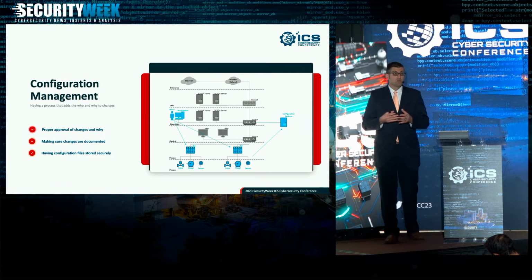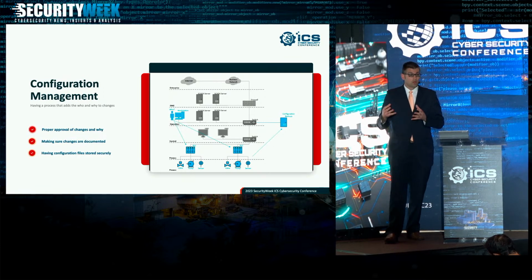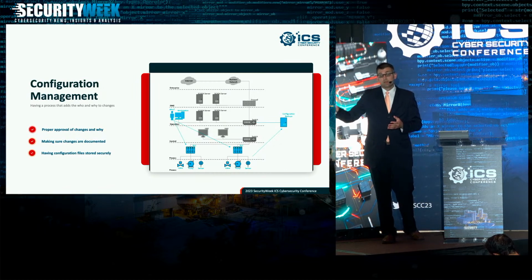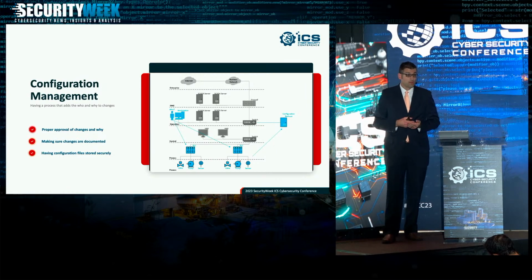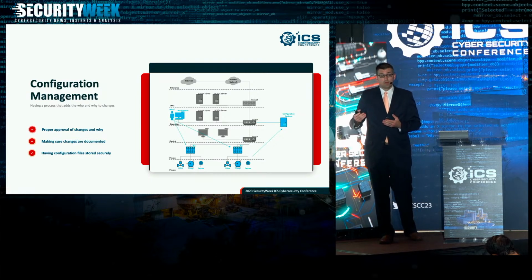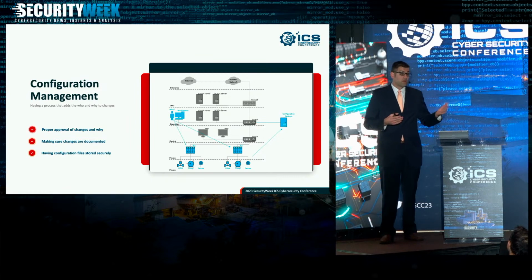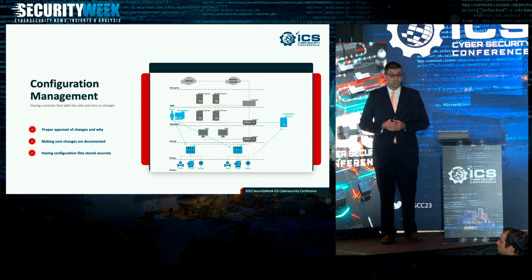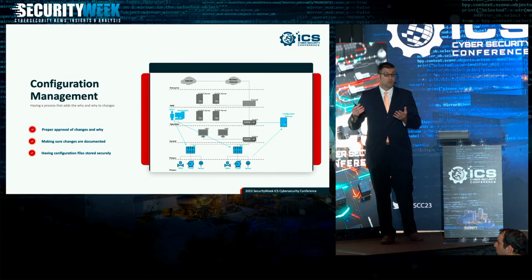All that context really gives us insight into our OT system and into our assets. For instance, is somebody that's not supposed to make PLC firmware updates trying to make a PLC firmware update, and why, if they are? Is it happening from a workstation that normally doesn't make those changes, that we've never seen make a PLC firmware update before? If so, has somebody gained access to that workstation and is trying to update the firmware to a version with known exploits that they can then use to get control?